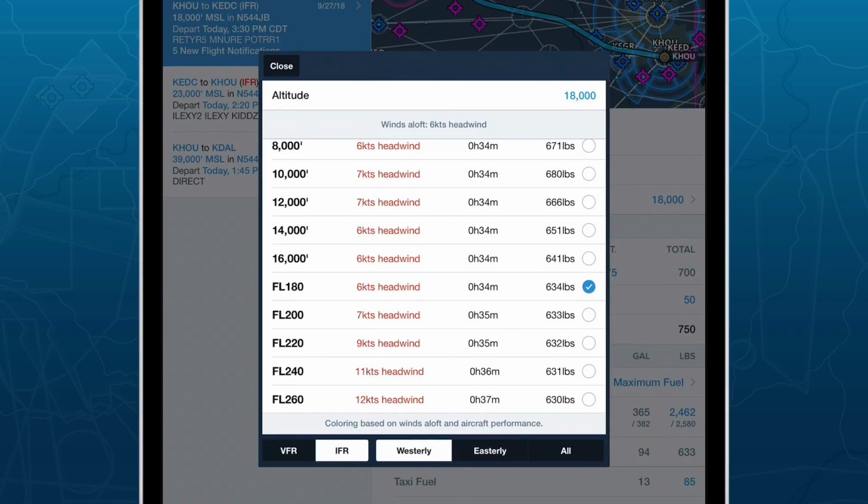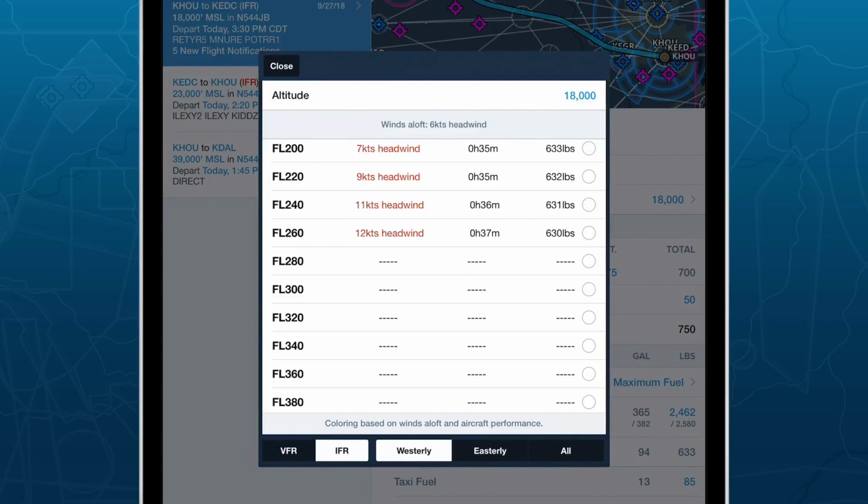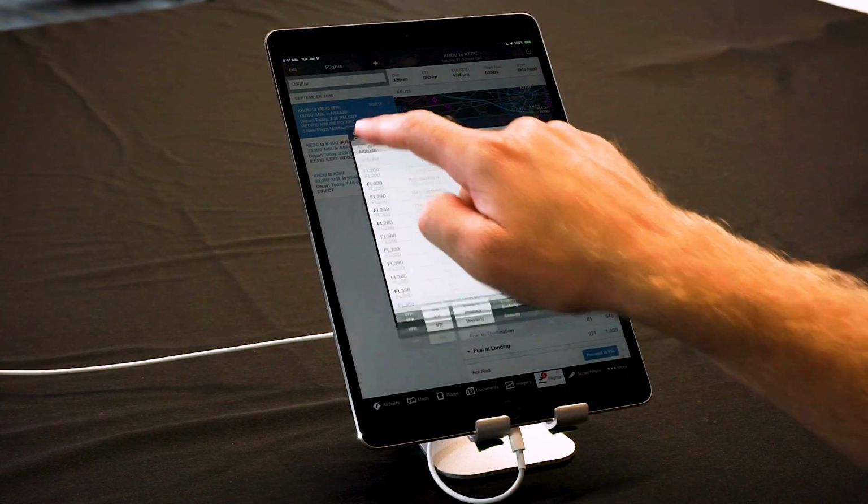The altitude advisor wasn't something that I showed earlier, but this again is giving you flight plan computations at every single altitude option for the airplane, giving you headwind component, what the total flight plan time is, and the fuel as well. Again, this helps highlight the speed and the intelligence of the engine. We've computed flight plans for every single one of these altitudes very quickly, and not included flight plans that are above the altitude that the airplane can reach on this particular leg. So you can see in this case, flight plans above flight level 280 are excluded because the plane can only get to 260 for this short leg.